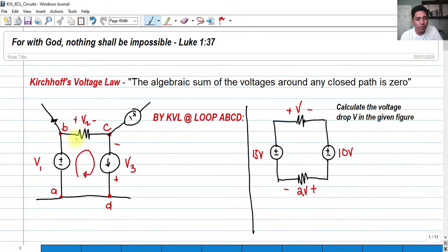It enters the left side of the resistor, though the resistor has no polarity. So we must label the resistor: since the current enters on the left side of the resistor, it should be labeled as positive to denote that the current is entering from the higher potential down to the lower potential.